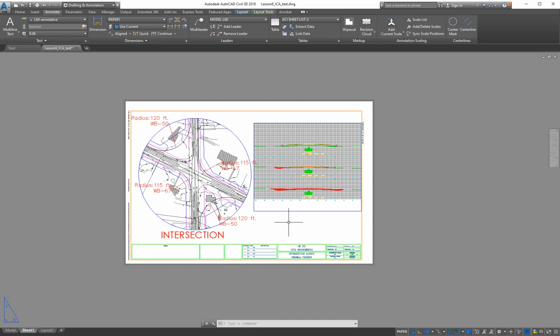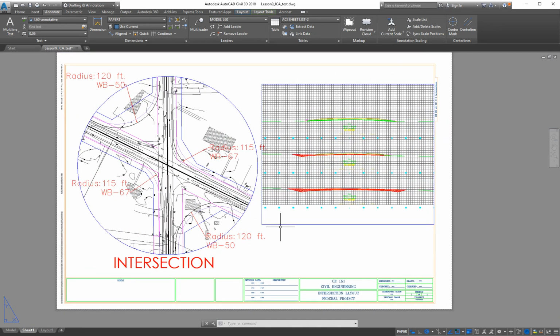And this is the actual way that you're going to make professional quality sheets, and pop these things out if you can get an internship, and even for your own classes, if you wanted to use AutoCAD, this is a way to make them look very professional, right? And the nice thing is, once you get these title blocks and borders set up, you can just copy and paste those suckers, and in fact, the entire layouts you can copy over and put into a different drawing and use it multiple times with different model spaces and different drawings. So once you find the title block and the layout you like, it's super easy to move it into other drawings and use it multiple times. Okay. So that'll do it for lesson 9 today.